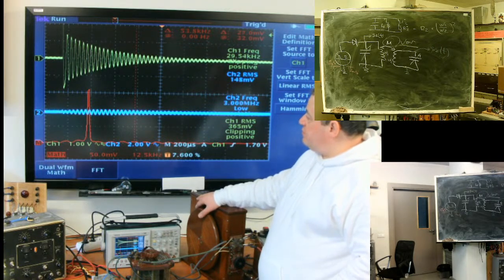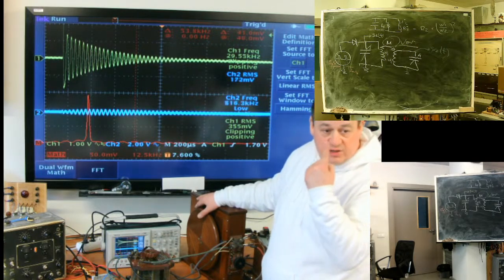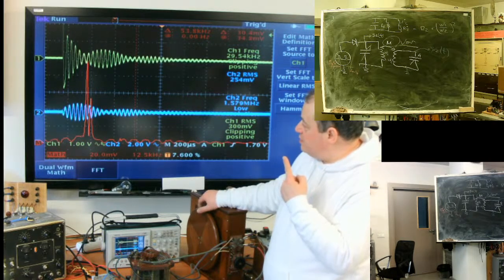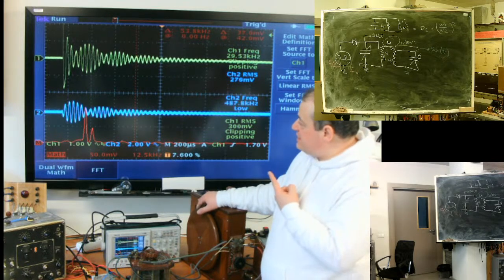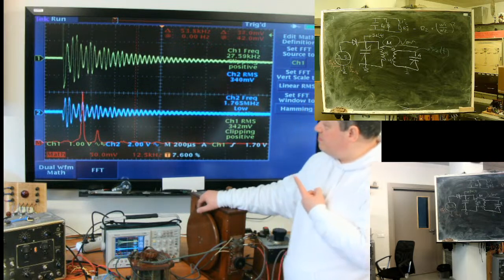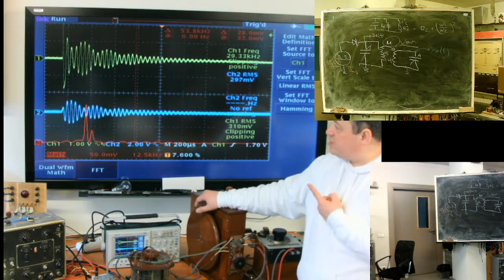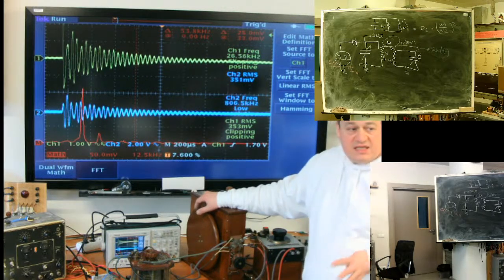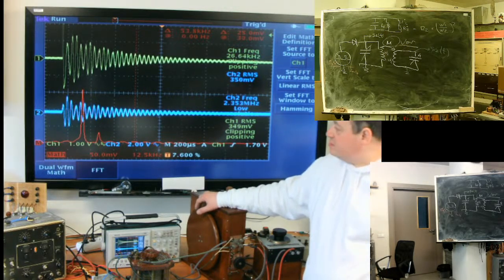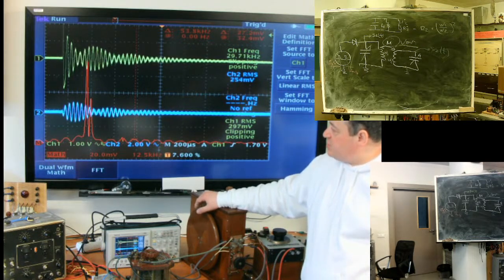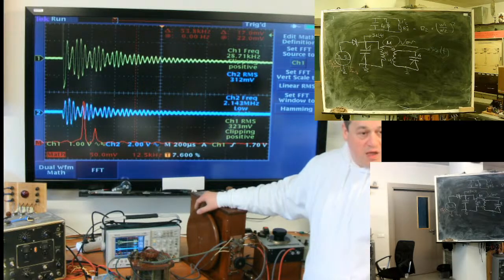When coupling is weak, we have one resonance frequency. With a stronger coupling, a second frequency emerges in the opposite direction. You see? The second frequency. This is a fourth degree network. Such a network has not one resonance frequency, but 2.